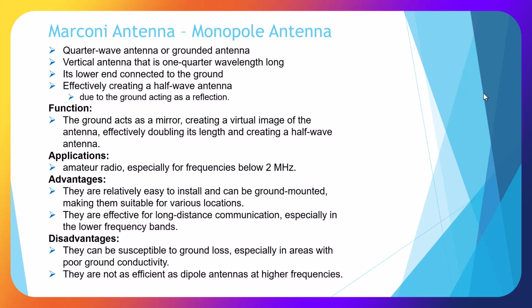The advantages are they're relatively easy to install, and they can be ground mounted. They're effective for long distance communication. And the disadvantages are they could be susceptible to ground loss, especially in areas with poor ground conductivity. They are not as efficient as dipole antennas at higher frequencies.